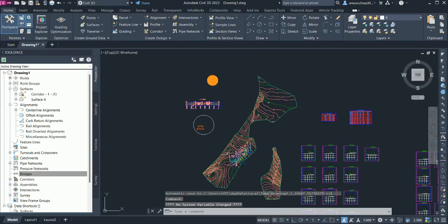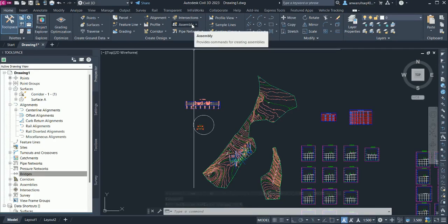A corridor is a combination of an assembly, meaning the cross section, and then the alignment and profile. If we have no profile, we cannot prepare the corridor. The corridor is actually the built-up surface, which includes side slopes, carriageway, side ditches, medians, whatever is included in the road.